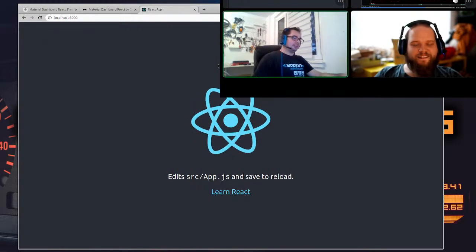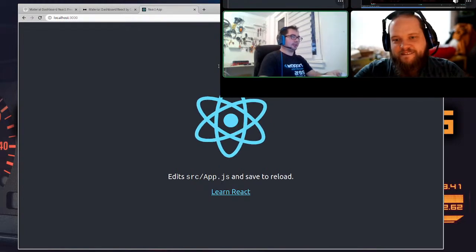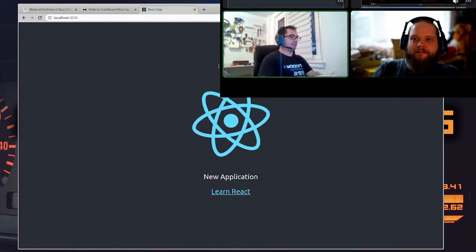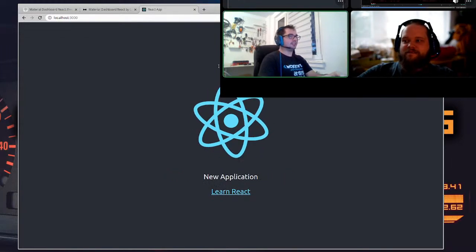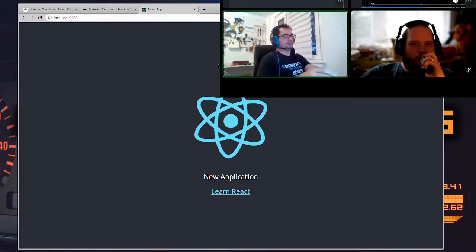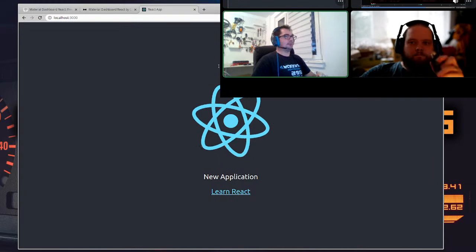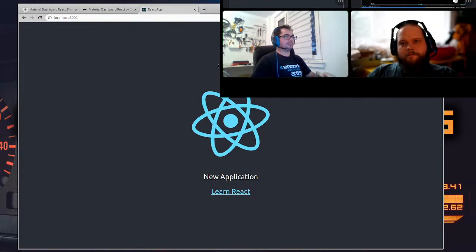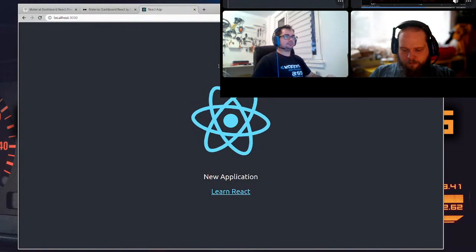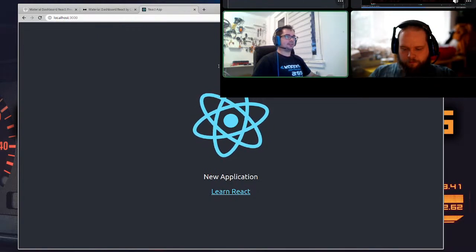Yeah, it worked, but I heard that it does not automatically correct some checksums, so you can badly flash something and destroy your ECU. Okay, not destroy, but you need to open it up and hope for the best that you can repair it. So something like that might happen.